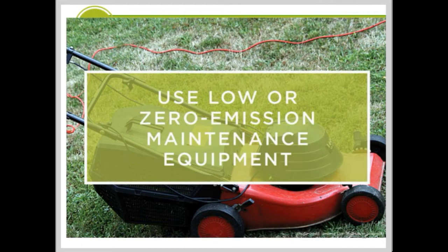A major component of site management is the type of maintenance equipment used. Gasoline-powered equipment contributes to greenhouse gas emissions and can cause noise and air pollution, reducing occupants' health and comfort. Therefore, the next step under the credit is to inventory the current equipment used. Review the site's current conditions and maintenance equipment. Inventory all equipment used, including any equipment brought to the site by contractors. Identify which items, if any, are powered by gasoline.